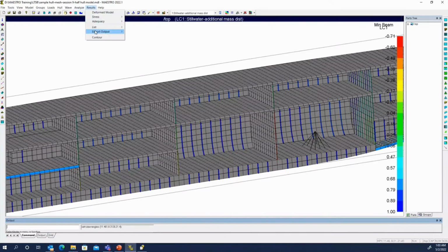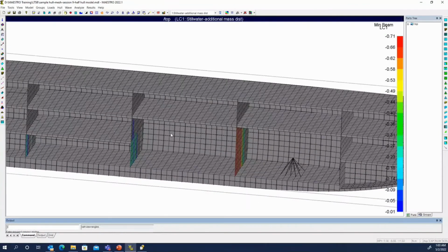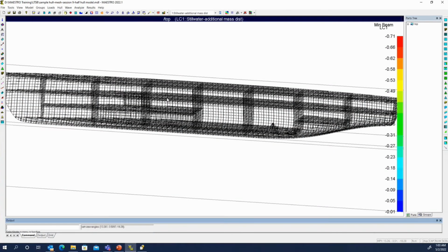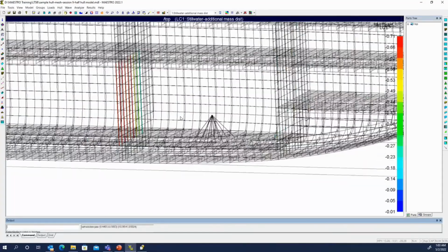And here, if we tell it I only want to see negative values, it makes it a little easier to see, but because those beams are so small, you might miss something. So one thing we can do is to turn off the hide elements outside of range. And now we have just a wireframe. But again, these are a little on the small side.